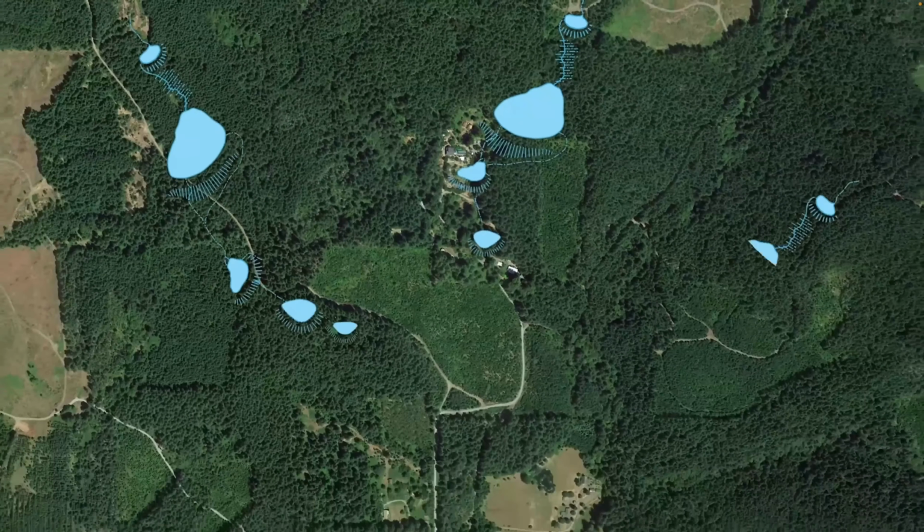Another field test is to look at water percolation by putting a nice gentle slope into your test pit, which is also really important, as an aside, to protect wildlife and critters and humans from falling into the pit and not being able to get out. You can use a nice slope to put in test holes for soil percolation.